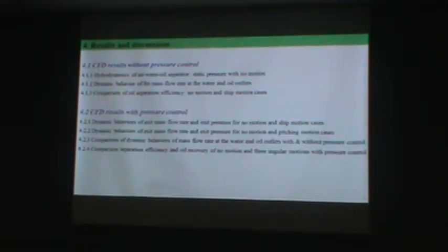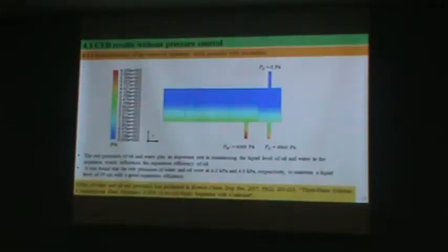Now we move on to results and discussion. The first part is the CFD result without pressure control. Note the outlet pressure of oil and water play an important role in maintaining the liquid level of oil and water inside the separator, which influences the oil separation efficiency. In this study, the outlet pressure of water and oil was fixed at 6.0 kPa and 4.9 kPa respectively.